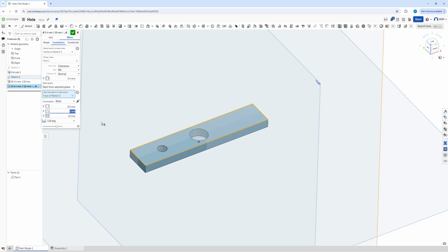So if I take this to 1, the counterbore, as you can see from this diagram here, has a wider top bit followed by the bolt that is narrow. Okay, and that allows the top part of the bolt to sit flush to your workpiece. So if I made it 2, if you imagine the bolt was pushing through, the top of the head will sit nice and flush into the work like so. And that's again the distance, 10mm, the diameter of the top, 6.5, and your angle, we can go flat again, depending on what we want to do. So that is the counterbore.